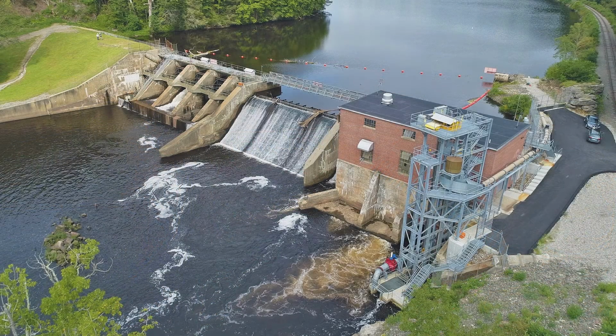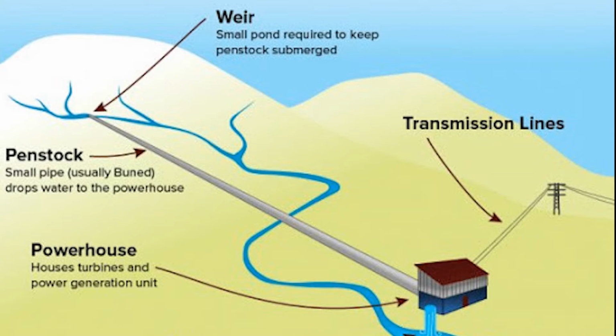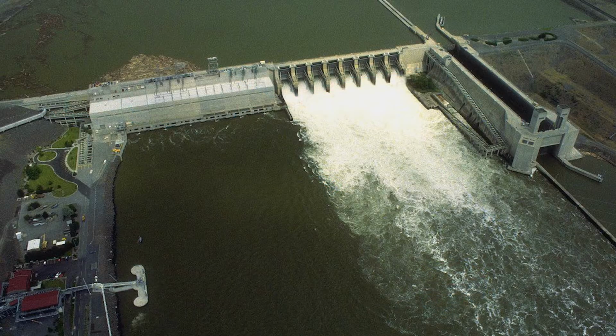Run-of-the-river hydropower is a similar concept to tidal power. Run-of-the-river produces electricity through the flow of a river through a power plant. There's no reservoir to collect water, so any excess water passes through the plant without contributing to the energy production. Because water levels in rivers vary seasonally, run-of-the-river plants are not always a reliable source of energy production. Between these four types of hydroelectric energy production, approximately 1/6 of the world's power is produced, with a majority of it coming from conventional hydropower plants.